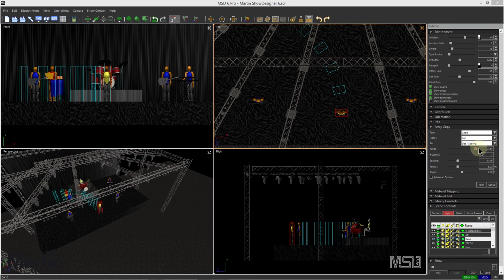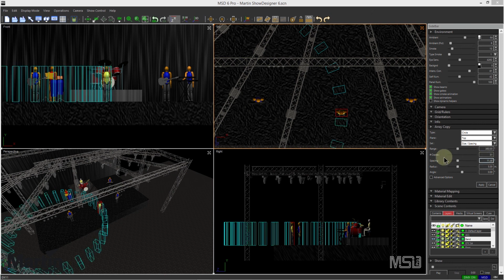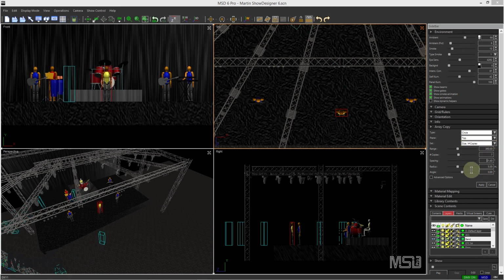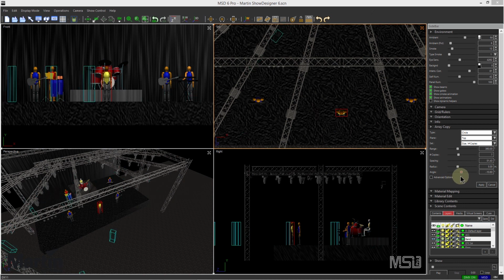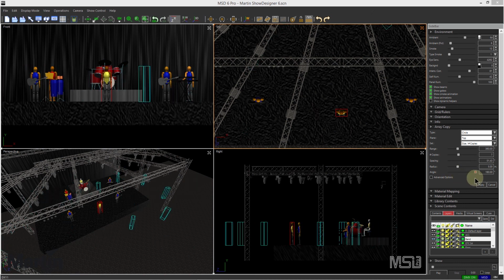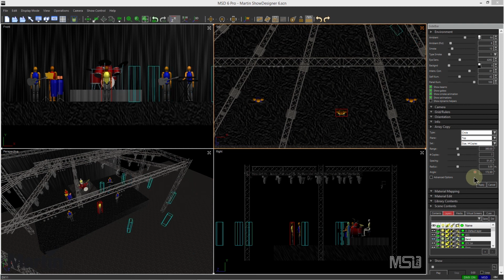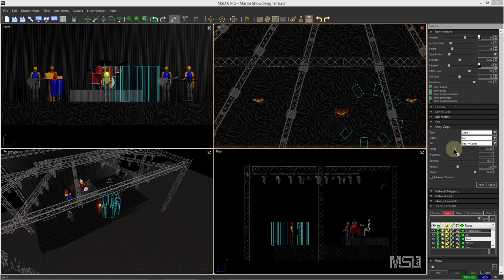So the range will be 360. And then it will tell you how many copies it would take with this radius to fill up. Or you could say using the number of copies instead. And then it will spread them. You can choose where the copy is in the circular, so we can see in the 3D view, you can choose where the copy goes. We can change the radius, so let's make this smaller here. So you see, it could be over 180 degrees.